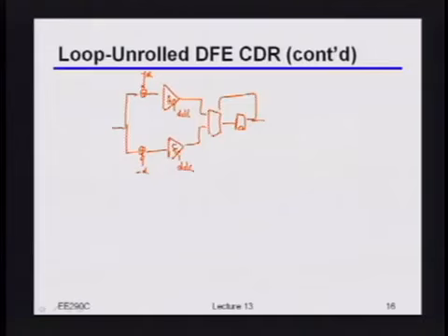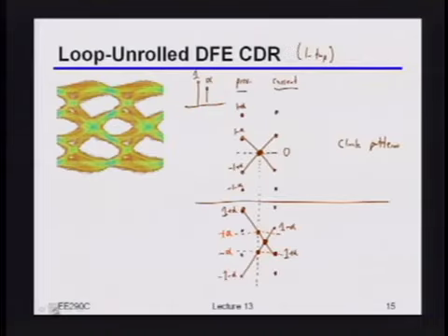Okay, but now what we're basically saying is that if we want to do clock recovery for this thing as well, then if we really want to, again, use every single one of those edges and make sure that it has the best possible timing information, then notice we actually need 3 different thresholds. We need one at 0, we need one at plus alpha, and one at minus alpha.